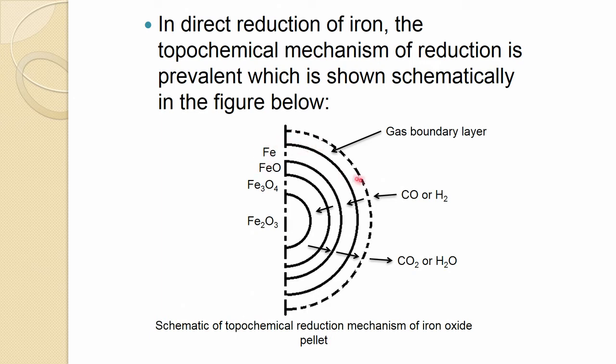the iron. Now, iron on the surface, so hematite has reduced into the iron on the surface. Now, CO has already reduced iron, there is no more oxygen left which it can remove. But still there is lots of part which is unreacted. So, what happened due to this removal of oxygen, this iron becomes porous, whatever iron is formed. So, CO or hydrogen has to diffuse now through this iron